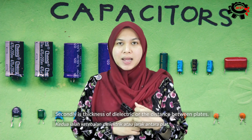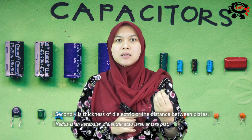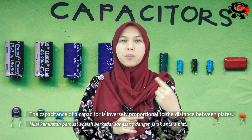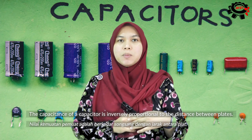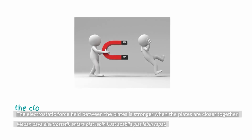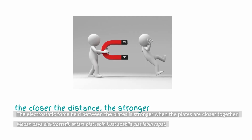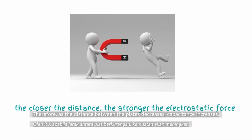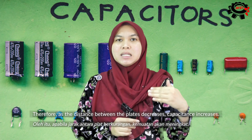Secondly is thickness of dielectric or distance between plates. The capacity of a capacitor is inversely proportional to the distance between plates. The electrostatic force field between the plates is stronger when the plates are close together. Therefore, as the distance between the plates decreases, capacitance increases.